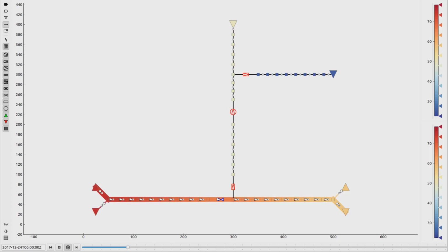We will see that the bottom valve will already close before the flow at the bottom is completely shut down. We do this since the pressure in the bottom right and the top area have to be equalized, and the still withdrawing exit can do the job for us. Furthermore, we see that now the compressor station has been turned on, since the top exit is withdrawing gas and we have to fulfill the minimum pressure requirement.